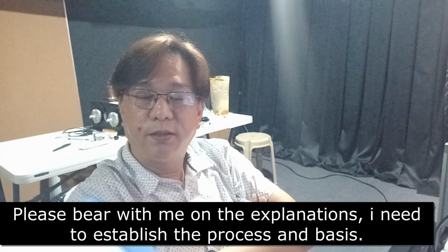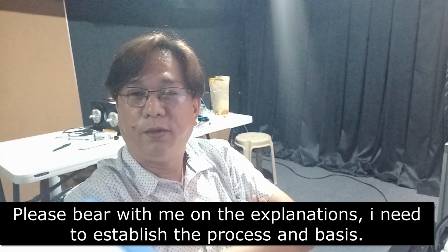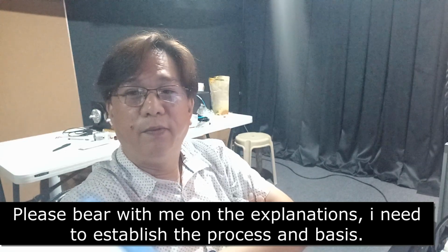So it's not just put a high power transmission system in one location and then that's it. So these are two of the relevant parameters that you should consider. Consider the height of the receiving antenna to match with your planned ERP.